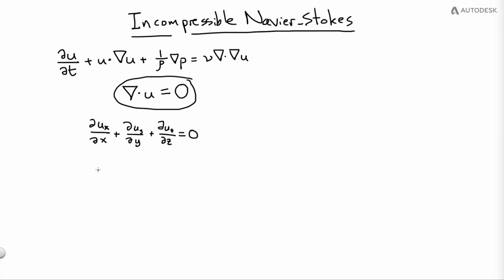What does that mean? Well, I'll just draw this, looking at, say, a little volume of space, a grid cell. Really what's going on here is this derivative, this difference along the x-axis, is basically saying if this was a super tiny infinitesimal cube in space through which the fluid is flowing, I measure the velocity on one face and subtract off the velocity on the opposite face in the x direction.